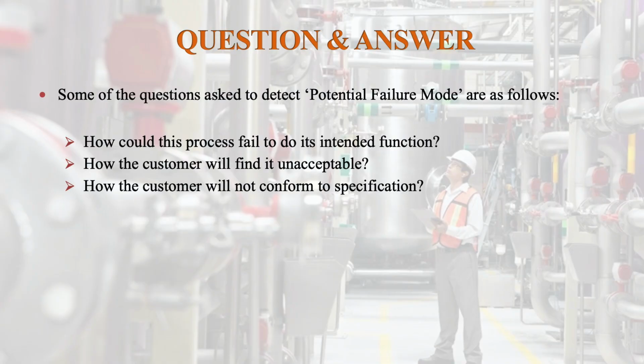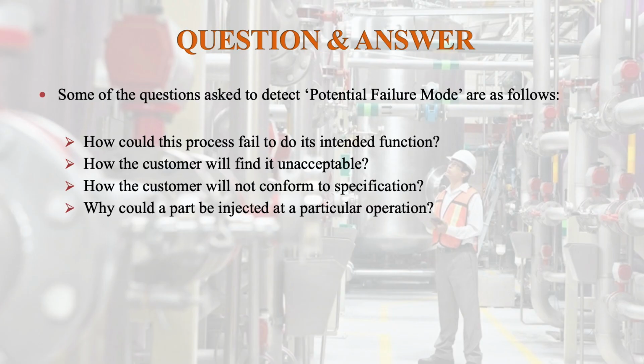How will the customer find it does not conform to specifications? Why could a part be rejected at a particular operation? These are the various questions one has to ask while performing a failure mode analysis to find out the potential failure modes.